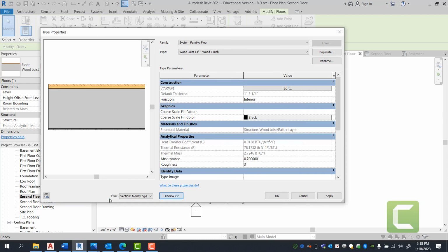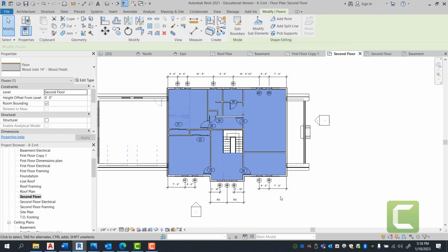And this time, if you look at the preview, you have added an additional gypsum board wall layer, or, I always say gypsum board wall, but it's a gyp ceiling layer. And this will allow you to have a ceiling being drawn directly from the floor. You're going to go ahead and press OK, and thereby you have created the ceiling for the first floor plan.